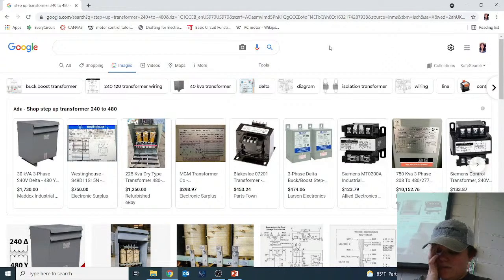To measure the input and output voltages, if a transformer is connected in a circuit, it can be tested by measuring the input and output voltages. The transformer is good if the input and output voltages are reasonably close to the theoretical values. So if they are close to what they're supposed to be, because nothing's ever perfect, that transformer is still good. So something else is going on, right? The current levels are tested if the voltage does not stay constant. Although the initial voltage may appear normal, it may not hold up when the transformer is fully loaded.